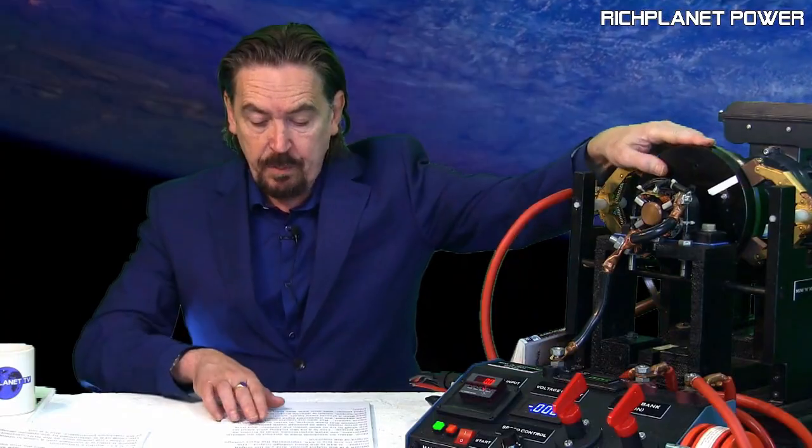Now, when an electrical load is applied to an electric generator, the shaft experiences what is known as back torque. This is a bit like putting your hand on the shaft to try and slow down the rotation, and thus the drive motor has to provide more power to overcome that back torque in order to maintain the same speed. But with my machine, when the load was applied, the measured input power was 33% less than it should have been, which means that the back torque, which is directly proportional to the input power, was also 33% less than it should have been.